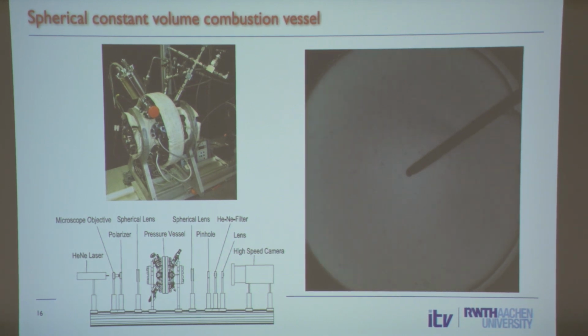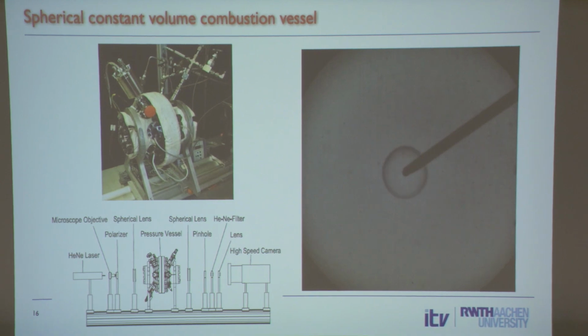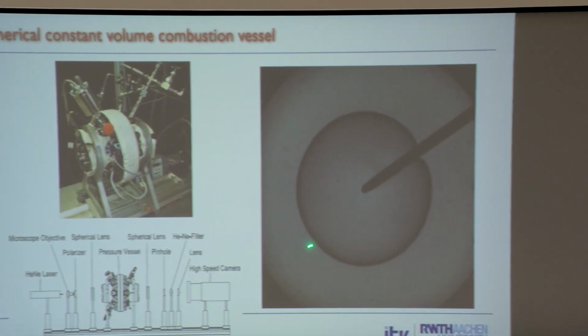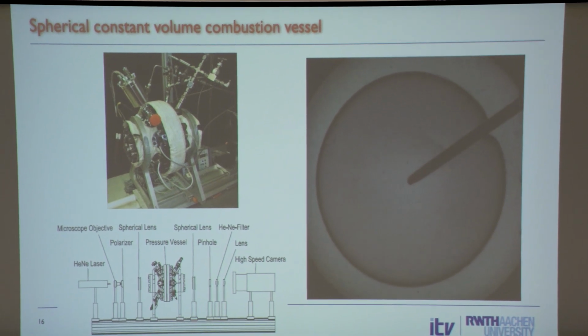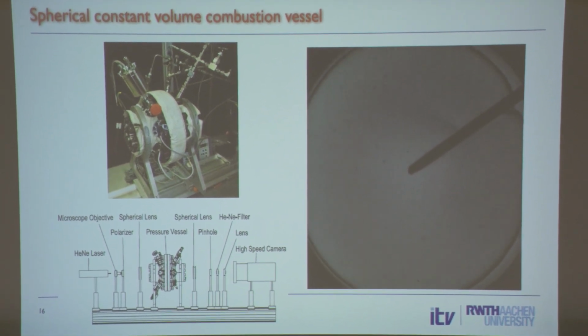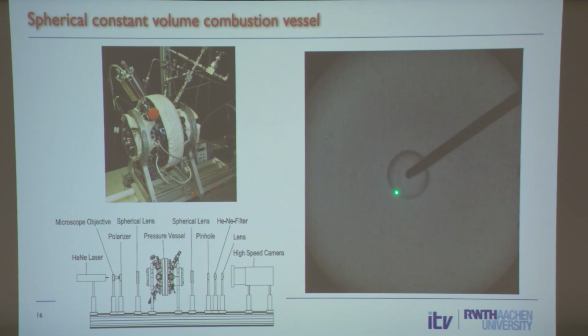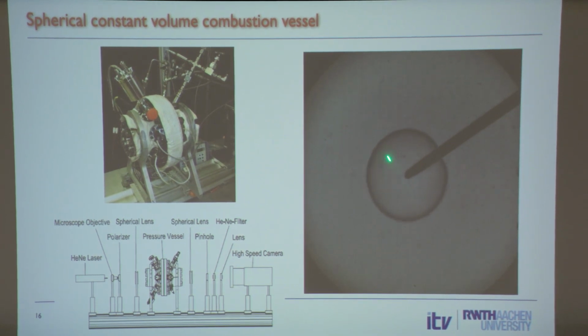And again, this is actually what you see now, because in the burned, the velocity is 0. In the unburned, the velocity is large. It goes away from the flame. What you see here is the burning velocity with respect to the burned. Okay, so that's typically much higher than the burning velocity with respect to the unburned.